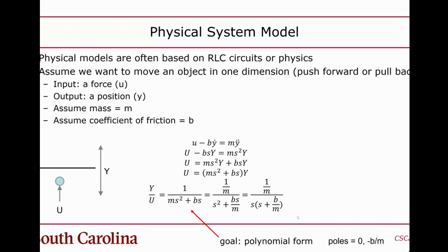There are methods where you send in a sinusoid input signal and look at the output, you sweep the frequency of the input and use that to construct the frequency response, and then convert that to a pole zero plot, and then use that to construct a transfer function. So you don't actually have to build plant models this way. You can also build a plant model through a system identification approach.